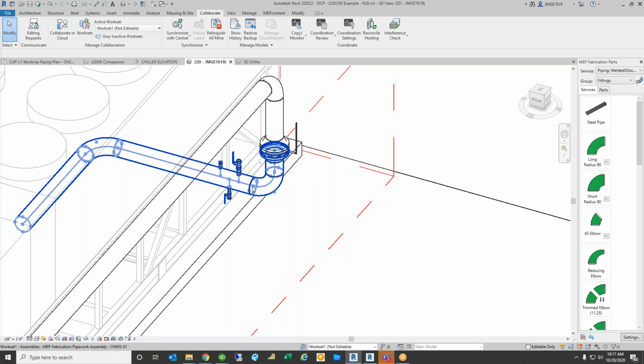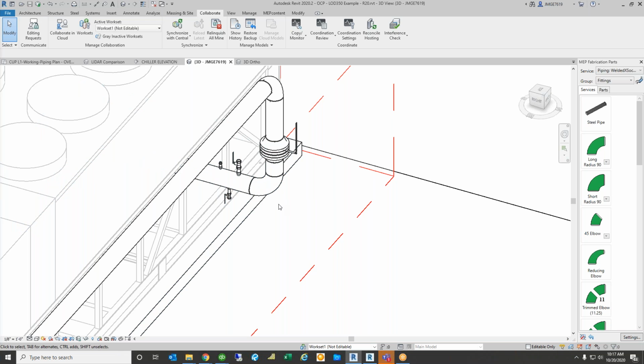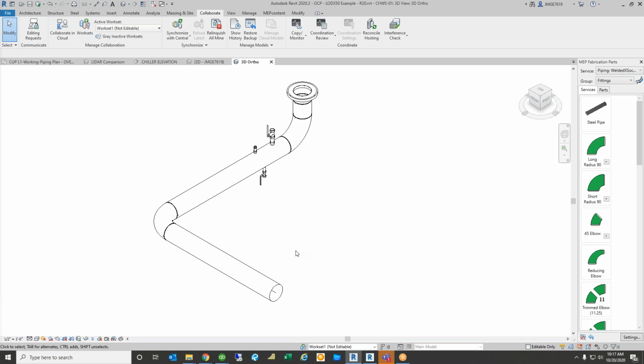And in addition to that, these thick lines that you see here at these joints, that's a welded joint in the field. Revit will actually put in there the gap that ASME recommends be used for making this weld. So at the end of the day, I can create a spooling drawing, which takes this particular spool, has my flange, my elbows, my straights, my weldolets for my thermal wells, and or threadolets for the thermal wells, and for the air vents and the drain pipes and all this other stuff. And these thick lines are actually gaps so that this pipe and this elbow are the correct dimensions, so that this center line dimension to this center line dimension accounts for the ASME recommended gaps for performing these welds.